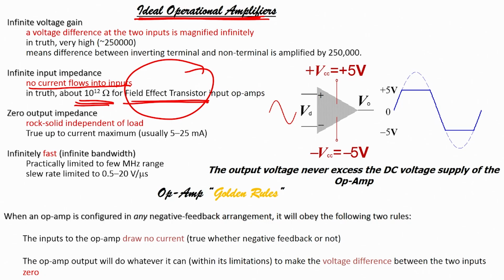So, also you have to see what is the first stage of the op-amp and what is the last stage of the op-amp. When we understand what is in the first stage, you will see that the amplifier designed in the first stage has extremely high input impedance, and the amplifier at the last stage has extremely low impedance, alright. So, that is why when we talk about the input impedance of the op-amp, it is infinite or extremely high.